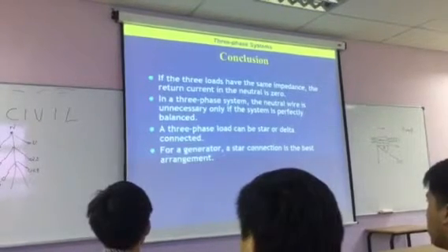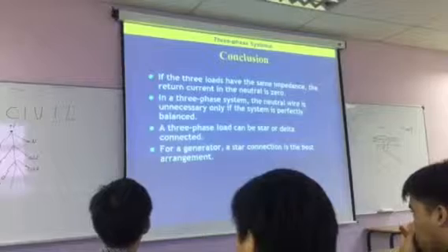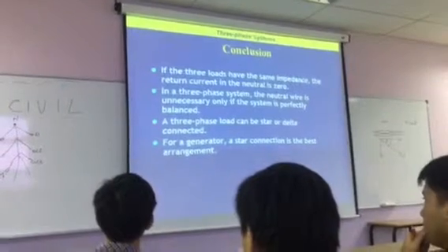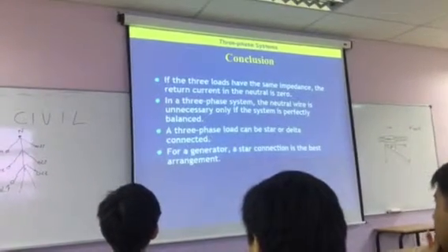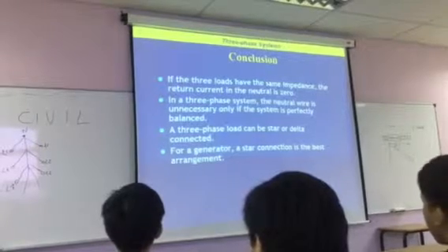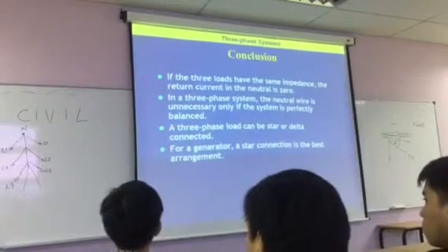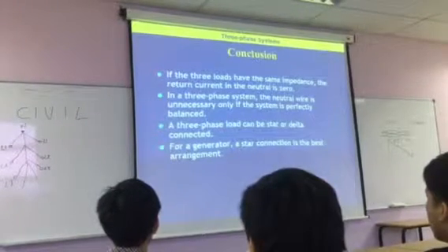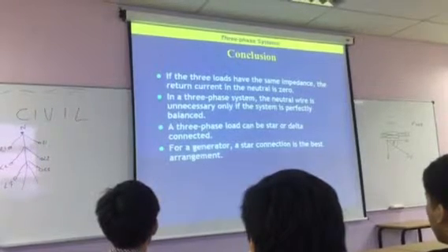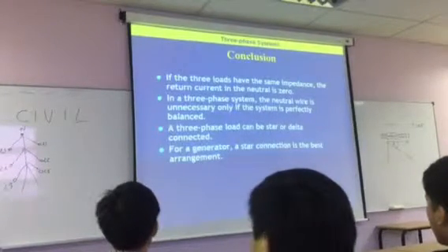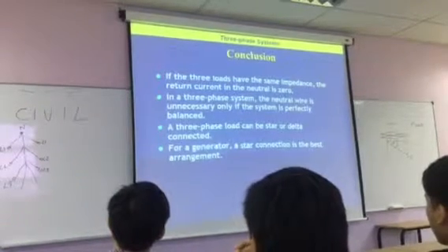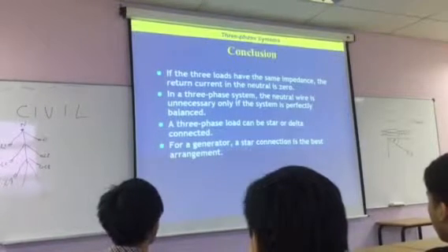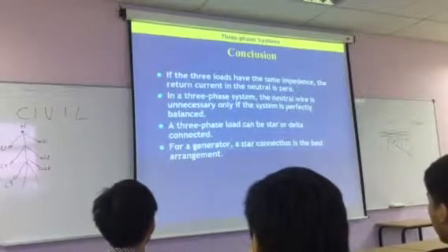Okay. Now, if you think about ways that can be achieved, it's balancing out the inductance and capacitance. So you can find that if you're generating the power using maybe some induction motors, you then may have to have some capacitor banks to balance the load. Okay, so that's how it can be done. Okay, but what I've said is that we have to take account of if it's slightly out of balance, so that's why we'll have a neutral wire.